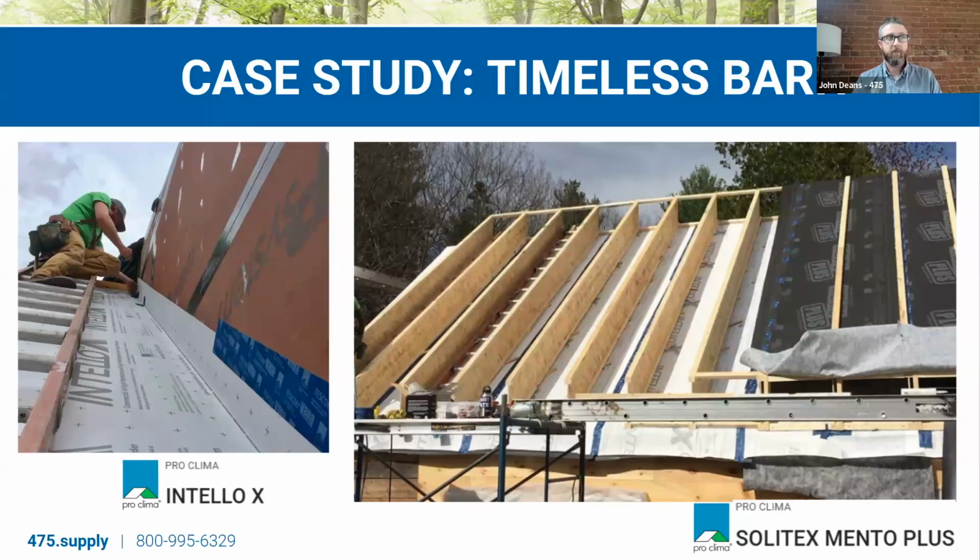And then we have 16-inch I-joists, and then the Mento Plus across the top of that, and then the battens, of course, creating the vent channel. You'll also see that if you look really closely, there are some shims under those rafters. This assembly allowed us to get a pretty flat roof over an old roof that was definitely not flat.